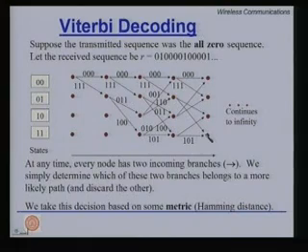So the philosophy is as follows: an input bit stream comes in and we keep matching it branch by branch with the inputs that are written on top of the branches. As we proceed, and we will see it through this example, we keep on defining a metric and keep track of so far what are the most likely paths possible.